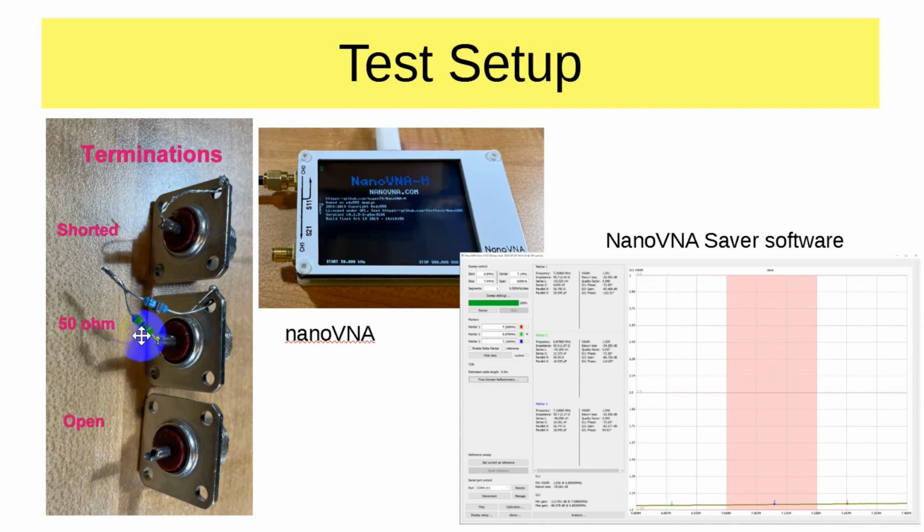That's a 47 ohm resistor and a 3.3 ohm resistor to get me close to 50 ohms. Another way that you could do that using standard value resistors is to put 2 100 ohm resistors in parallel. It will do the same thing. You see they're connected from the center conductor over here to the shield. And then there's an open one where there's actually no connection at all.